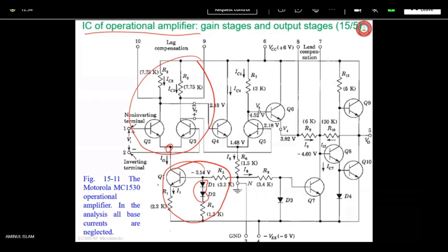What should be done? We know that there will be a loss of precious voltage picked up by this signal pickup or transducer or sensor. So the solution for that is the Darlington pair. We have seen that it has good input resistance, so that can be used in place of Q2 and another in place of Q3.